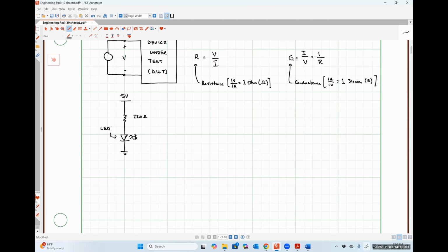So what the resistor was doing in this particular application is limiting the amount of current that can flow through the LED. The internal resistance of an LED is usually pretty small. So if you put a full 5 volts across it, it would drive so much current through it that it would literally fry the internal semiconductor material, burning it out so that you could never use that LED again. The resistor was there to limit the amount of current that flowed through the LED.